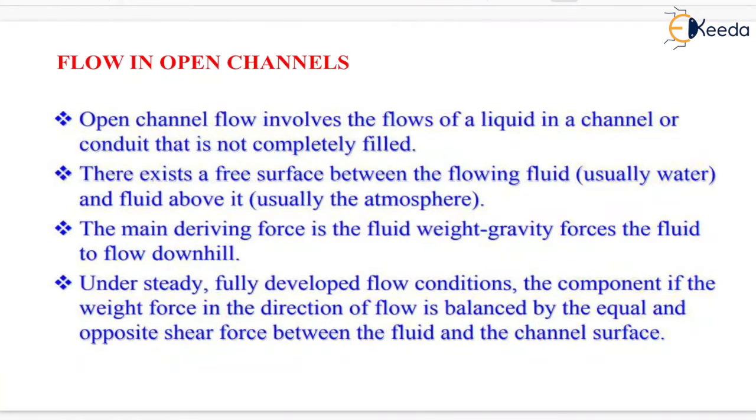Now, the first topic is flow in open channels. Open channel flow involves the flow of a liquid in a channel or conduit that is not completely filled. There exists a free surface between the flowing fluid, usually water, and the fluid above it, usually the atmosphere. The main driving force is the fluid weight. Gravity forces the fluid to flow downhill.